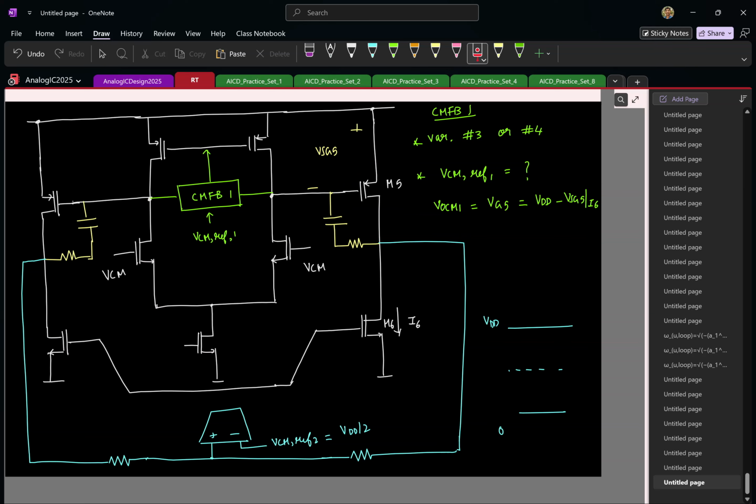Of course, you can do things to make that independent, but as of now the PMOS is basically fixed. The only choice you have is to control the gate voltage of the other transistor. So in this particular case, the PMOS current is fixed. We have to tune the current in the NMOS transistor so that the current here matches the current here. So basically, I'll do this. Correct.